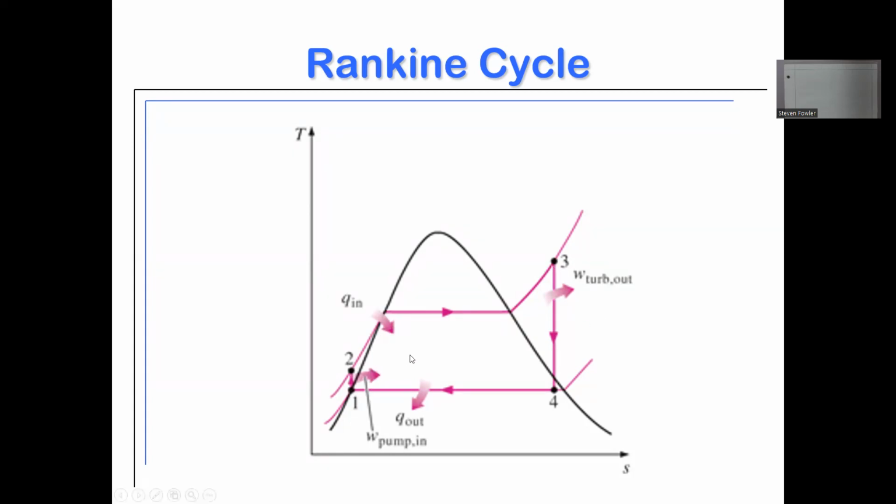And these are isentropic from 1 to 2, going straight up vertically with zero change on the entropy axis, and zero change from 3 to 4 in an isentropic expansion, dropping down to the lower pressure from 3 to 4 in the turbine. So again, you can see that graphically.